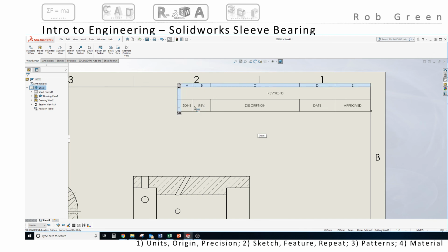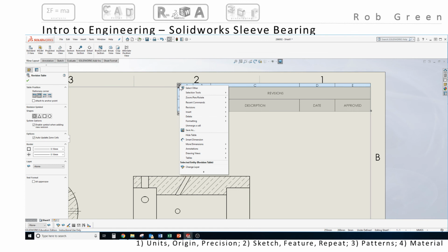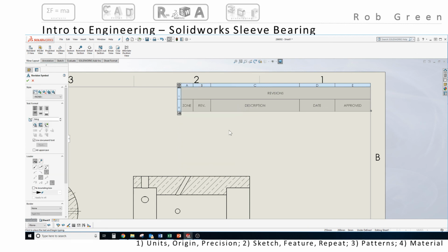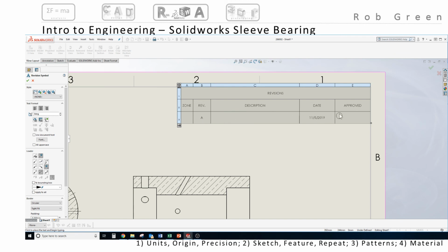Once I have my table, I can right-click on the table and say Insert, say Revision, and add a revision. Once I do that, I get a whole revision line called Revision A, and I get this little circle on my cursor that I can drag around for a while. If I click anywhere, I'm going to place a circle. I don't want to do that, and I will have explained why and what that circle is in class. In this particular case, I'm just going to move forward.